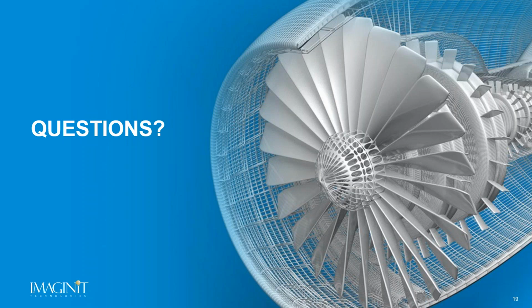Yep. So creating a family from Inventor, as me and Brian mentioned earlier, is static. I can create a family and it can be used, but it is not going to be adjustable. In Inventor, I'm used to the idea of having parameters and being able to flex something, but even if that's true on the Inventor side, once it goes to Revit, it is static. It is a single item. If you want to have flexible components, multiple sizes, that's best to be created as families in Revit, not as a family from Inventor. Yeah, that term would be a native Revit family for you there, Alex, in the chat.